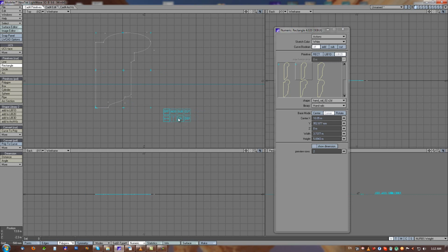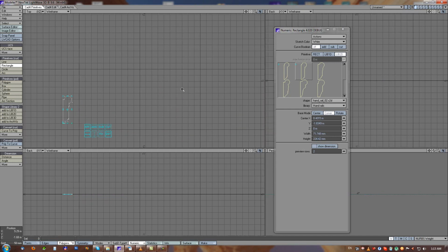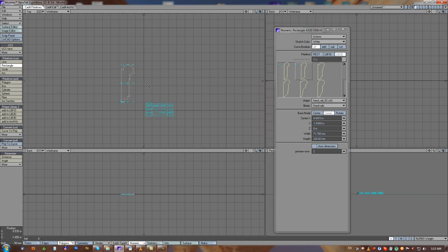With the fix button we can freeze the shape, so the shape is only moved now. When I unfreeze it by clicking the fix button again, I can scale the object. And the last button is a default button. With this default button, the shape is scaled into default parameters which are used from shape library.